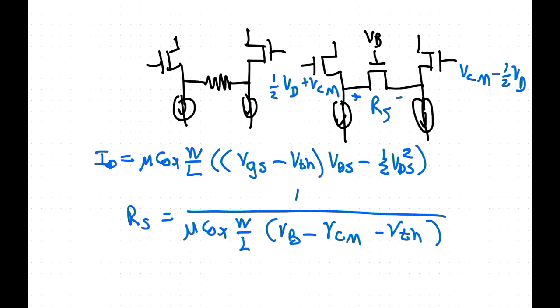But our bulk isn't tied to the source or the drain, it's just tied to the power supply. Yeah, but it'll still be true, that's just the definition of how you define it. Now, if the bulk is tied to a higher voltage than the source, you might forward bias the diode, but that doesn't change what is the source and the drain.